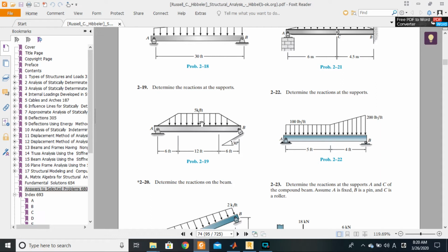Okay. So this is the exercise that we have as challenge today, and the question is determine the reactions at the support. We have just one beam. It is pinned at A and roller inclined at B. But the inclination here is quite interesting, right? So we have a perpendicular line here to the normal inclination, and it forms an angle of 30 degrees with the horizontal. So it implies that the roller itself forms an angle here of 30 degrees with the vertical, right?